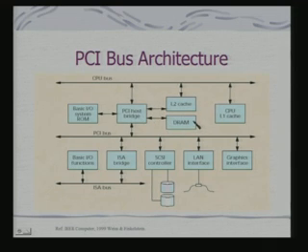We have already studied that DRAM is a slower device, and the CPU bus will be pretty fast because the CPU is working at a higher clock rate. So, the PCI host bridge provides the communication interface between the fast CPU bus and the slow DRAM device. In fact, it also provides connectivity to the basic IO system ROM as well.